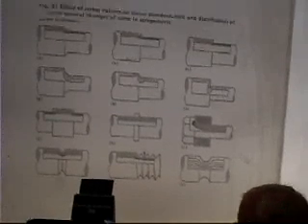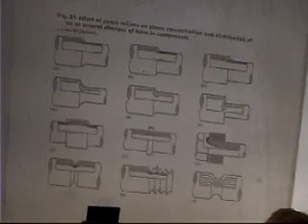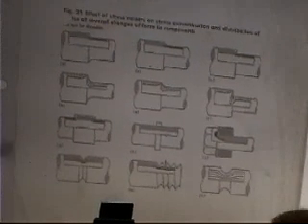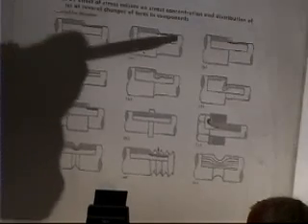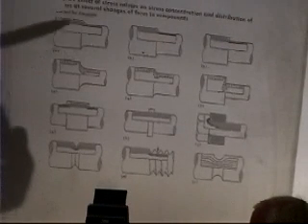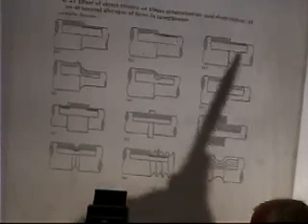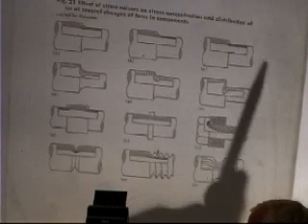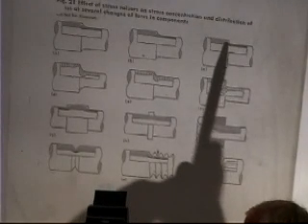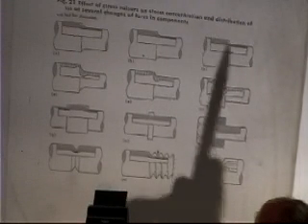Now, stress concentrations. Most of you, having worked in the real world, probably know what a stress concentration is, right? We're not talking about emotional stress here. We're talking tensile stress or compressive stress. But basically, whenever you have a change in section, going from one thickness or diameter to another, there's going to be a change in stress. And you can draw the stress lines, and the density of the stress lines tells you something about stress concentration. Whenever you turn a sharp corner, those lines are going to get closer together.